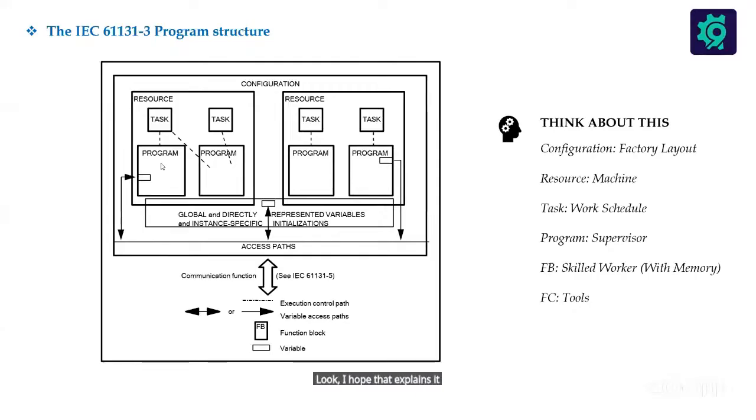So now, when your PLC is starting up, the operating system of your PLC is going to call on the OBs. At this level, it's going to call on the OB1. So the OB1 will now run the program from top to bottom, left to right, like we were explaining yesterday.